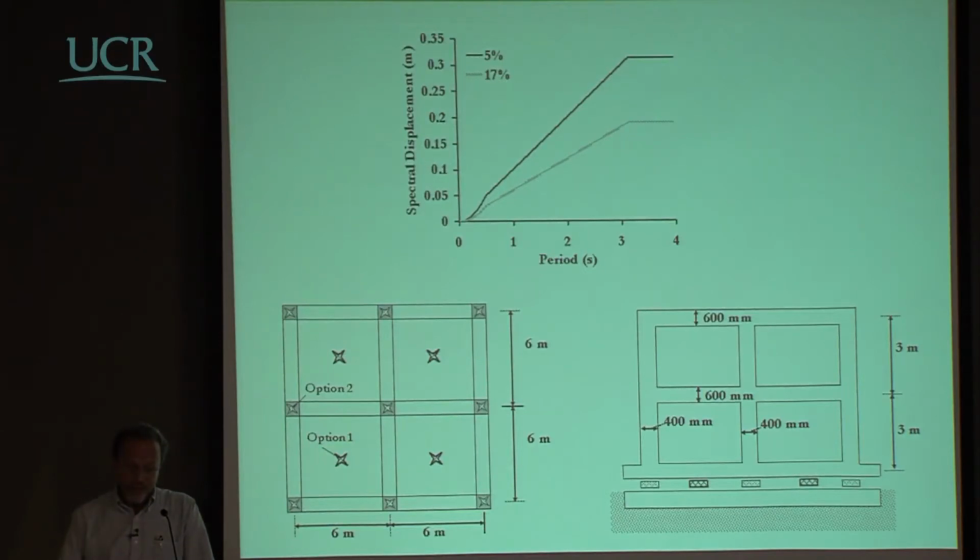So you may end up having a need of using maybe, I don't know, just 4 rubber bearings, and to use 5 pot bearings. Actually, pot bearings are more expensive than friction pendulum, so you may end up with something like that, finding that a friction pendulum isolation would be less expensive.